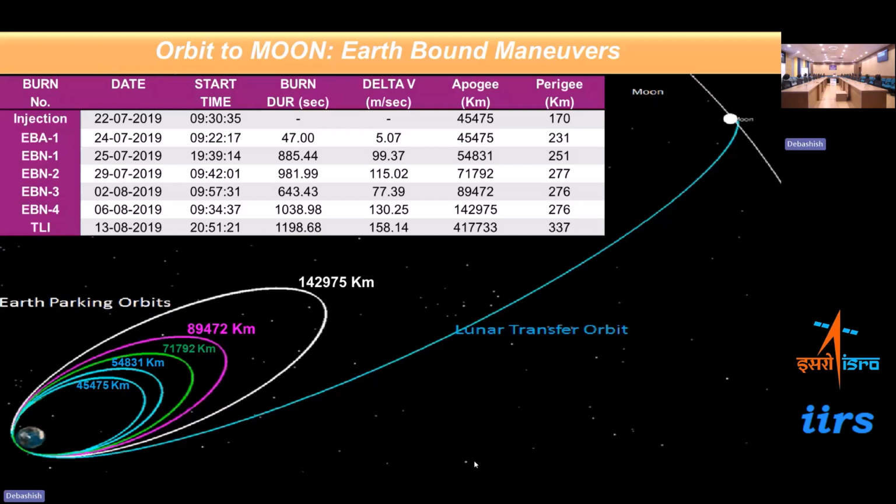Now, slowly we do orbit maneuvers one by one. Sequential orbit maneuvers will be planned. After the end of the maneuvers, the satellite will be very close to the moon. That's the intention. This is called mission planning. Here the planning part is important: at what time we should fire, at what place it is to be fired, when the moon is also rotating about the Earth. When my apogee is close to the moon, the moon also should be there. So here also timing is very important.